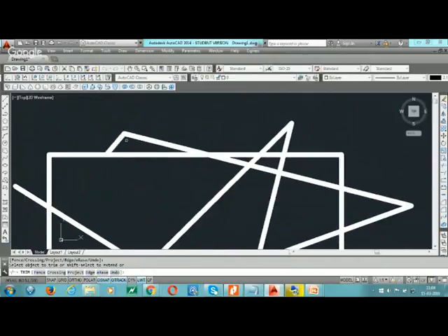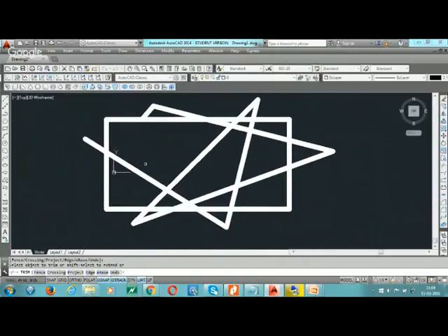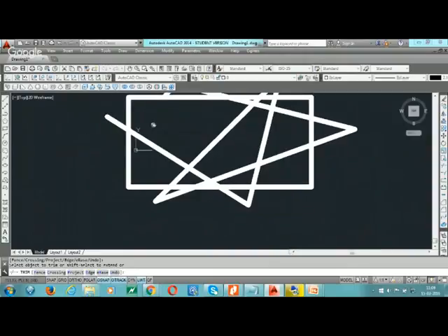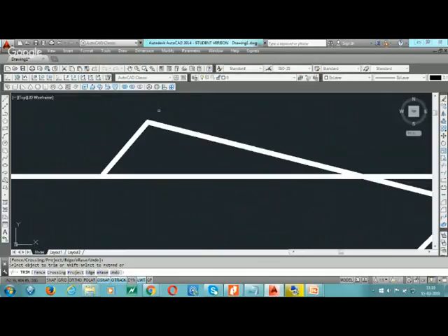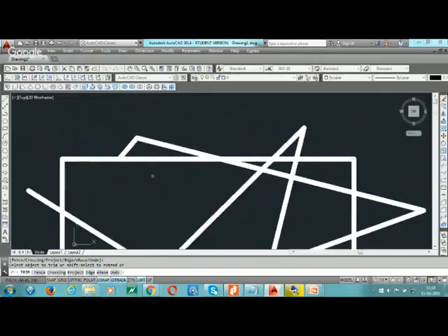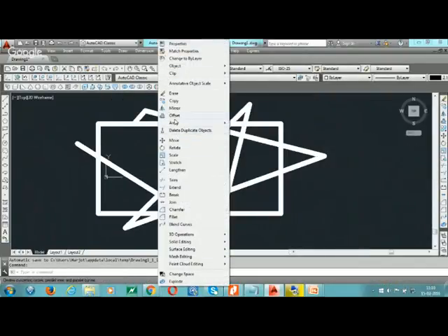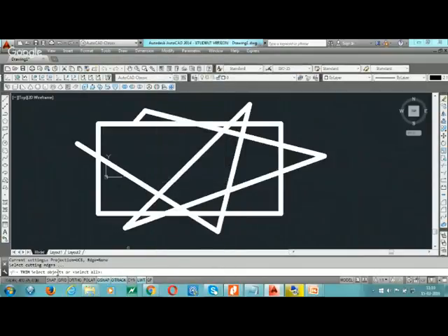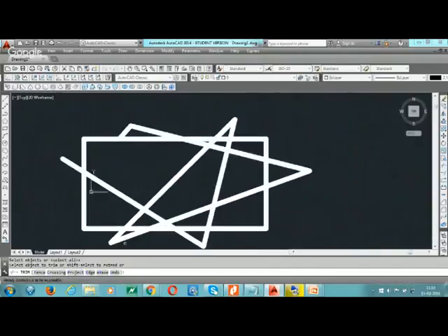But not at the end, because it trims like scissors. When we use scissors to trim the hair, it is trimmed like that. But here no further line is there. That's why the last line can be left. Again, go to the modify command, go to the trim command, select all, then trim, starting the trim from this corner to this, starting from this corner to this line.